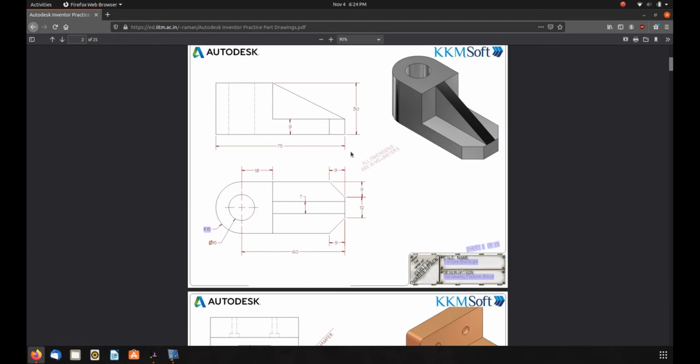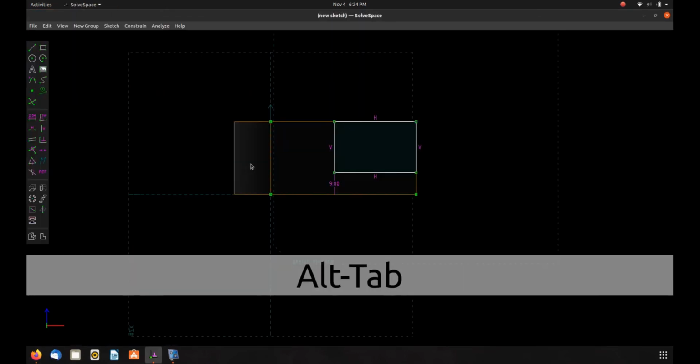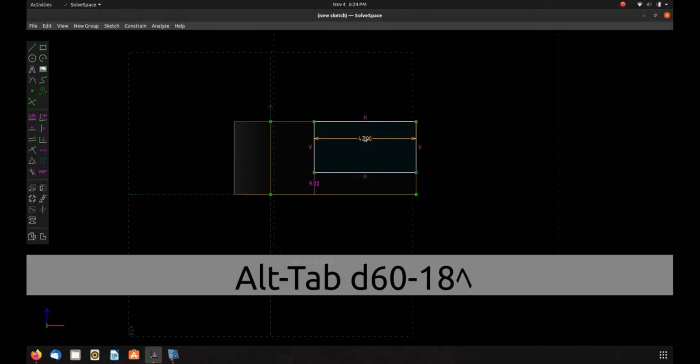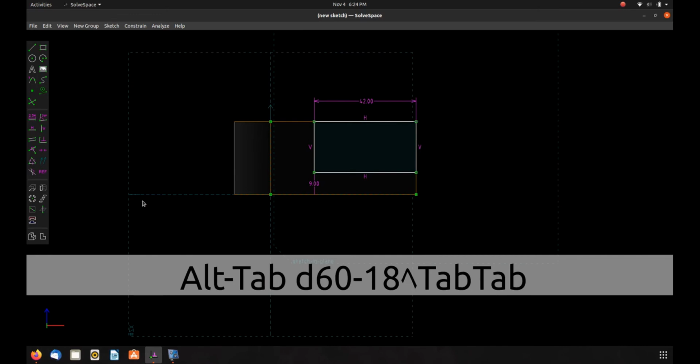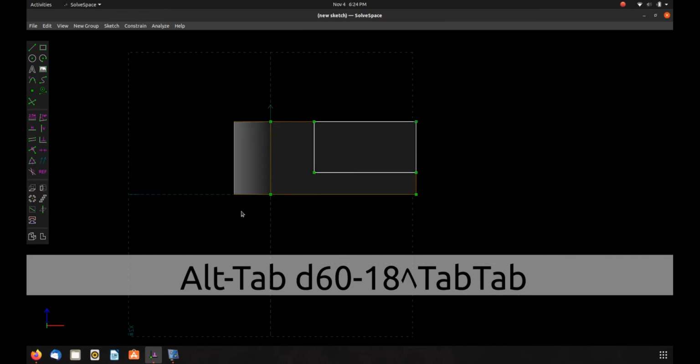I took this opportunity to show that SolveSpace can do arithmetic for you. So we know that is 60 minus 18 millimeters. So I typed that in here. Again, 0 degrees of freedom on this sketch. So we can go ahead and extrude by pushing that button there.